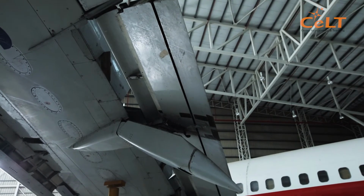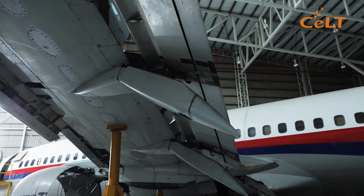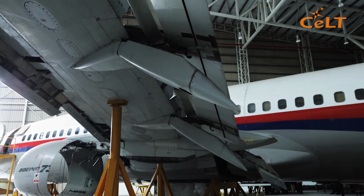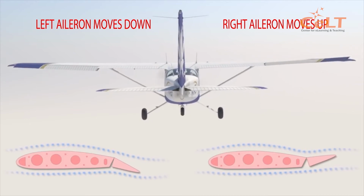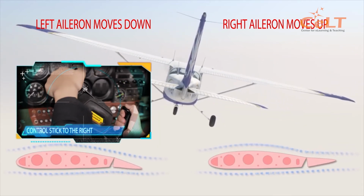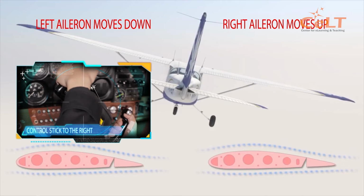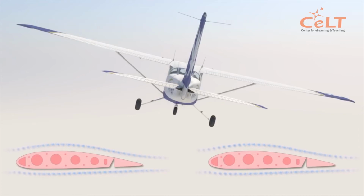Control surfaces, control and movement. Ailerons are used to roll or rotate the aircraft. When the pilot moves the stick to the right, the right aileron moves up and the left aileron moves down. This causes more lift on the left wing and less lift on the right wing. The difference in forces causes the aircraft to roll to the right.